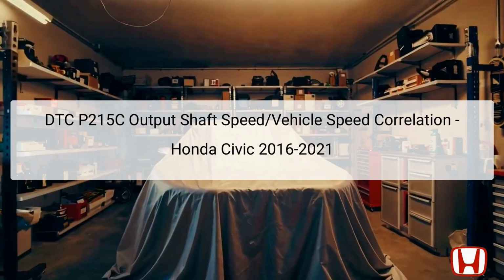DTC P215C refers to a correlation issue between the output shaft speed and the vehicle speed, which can affect vehicle performance and safety. The output shaft speed sensor, also known as the countershaft speed sensor, is responsible for monitoring the speed of the output shaft in relation to the transmission. The vehicle speed sensor, on the other hand, measures the overall speed of the vehicle, sending this information to the vehicle's engine control module, ECM, which utilizes it for various functions such as shifting and stability control.